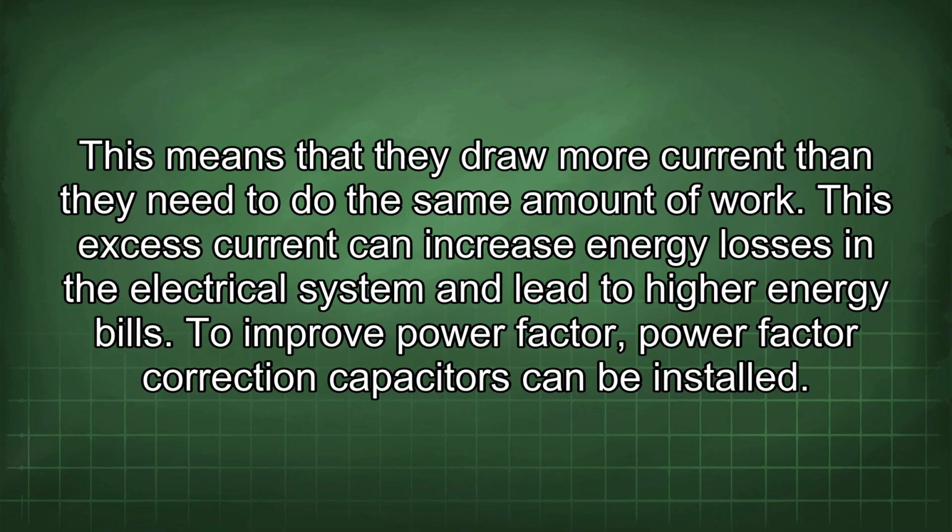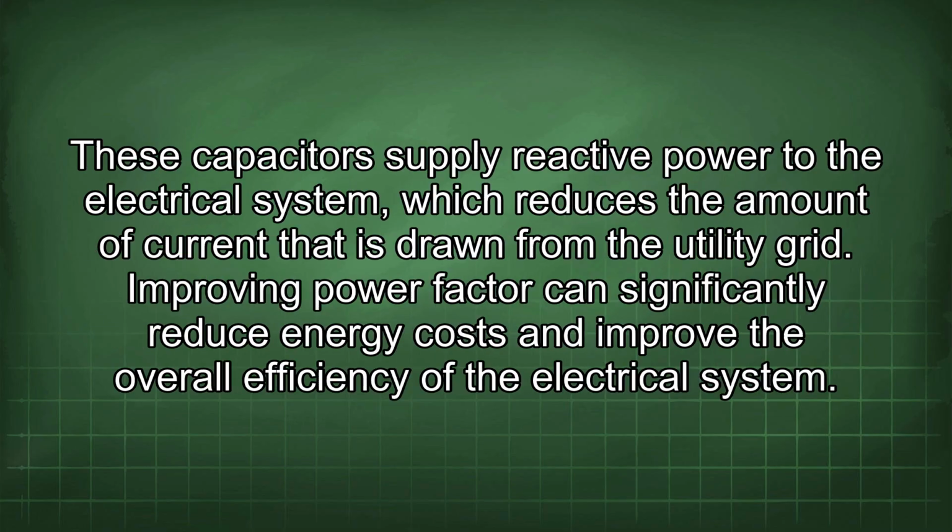To improve power factor, correction capacitors can be installed. These capacitors supply reactive power to the electrical system, which reduces the amount of current that is drawn from the utility grid. Improving power factor can significantly reduce energy costs and improve the overall efficiency of the electrical system.